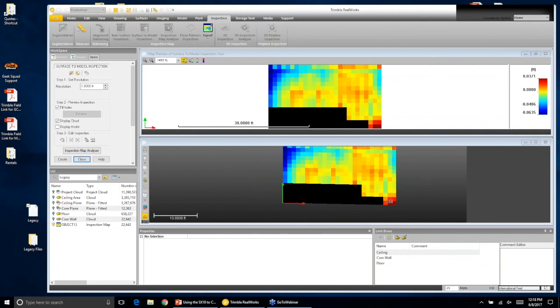And I do want to kind of accentuate one of the features that Matt was pointing out on that band scanning. When you choose a higher resolution and you want that band scanning to go back over the project several times, it changes the horizontal angle slightly. What we've noticed that we didn't anticipate over a traditional scanner is that with that band scanning, it tends to pick up edges and corners a lot better because it's actually going over it multiple times.